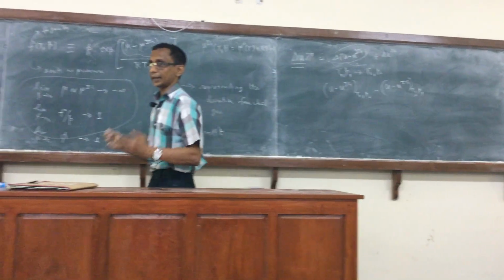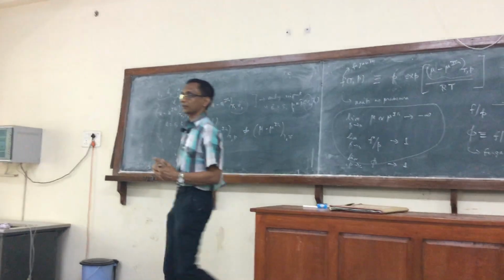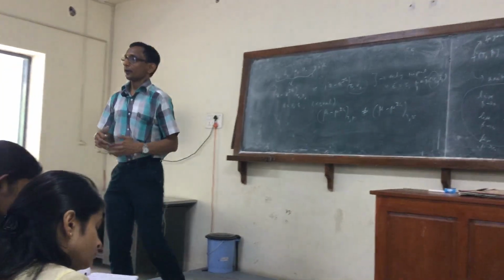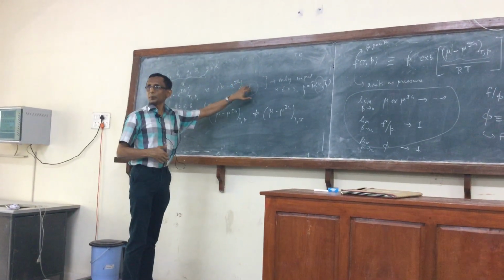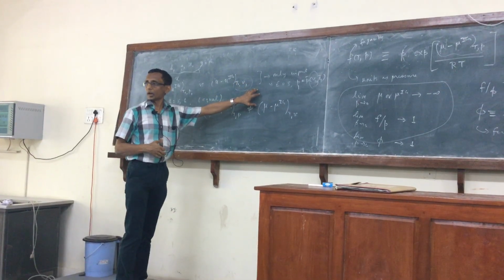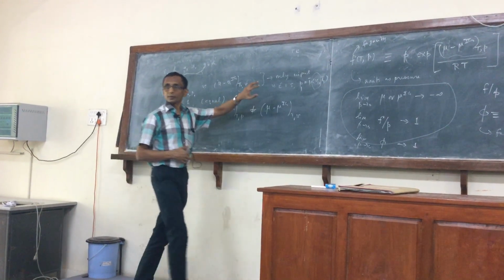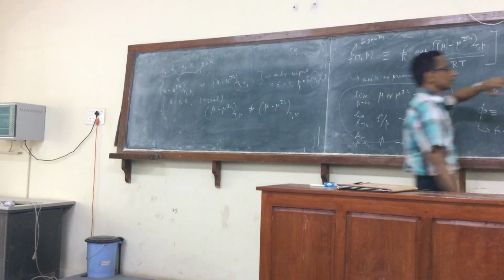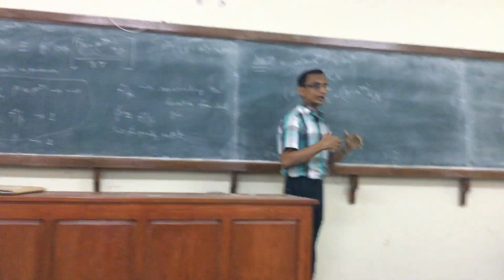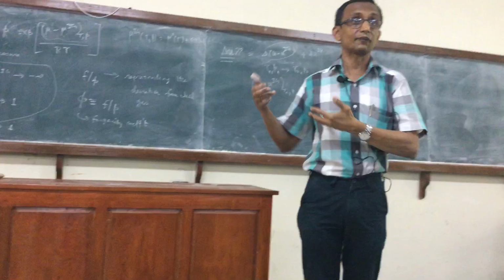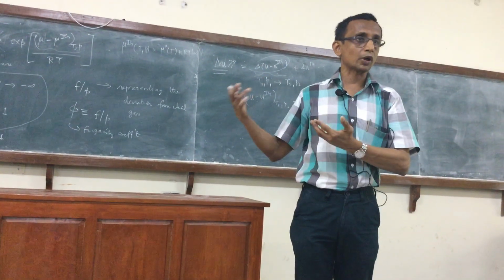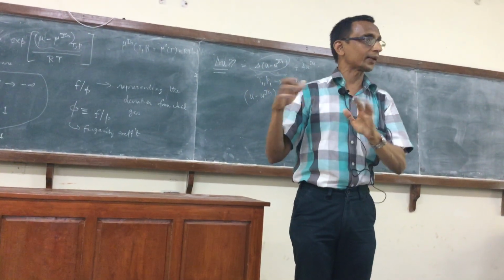That's what the delta signifies. So I know all the formulas that we have given involve T1 and P1, and of course v1 also would come in, right? So if I want to calculate it at some temperature T2 and P2, wherever T1, P1 appears, I have to put T2 and P2, and wherever v1 appears, I have to calculate the specific volume corresponding to T2 and P2 and substitute that.